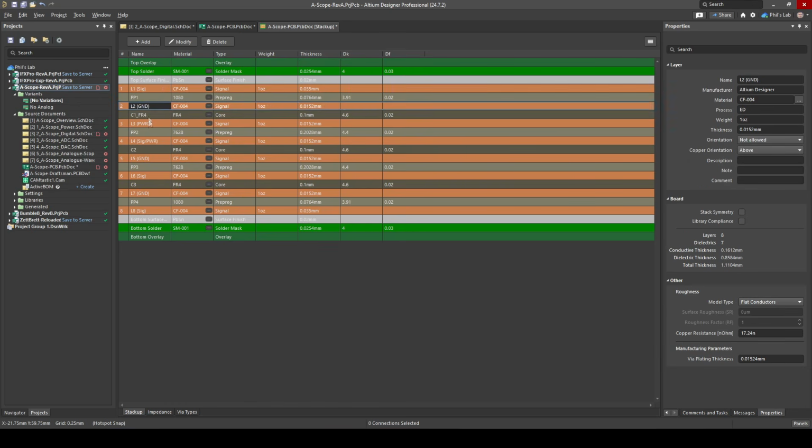Again, we have signal, ground, power, signal, ground, signal, ground, signal. So adjacent to every signal or power layer, we have a dedicated ground layer. So that means 3 of my 8 layers are entirely dedicated to ground. My main routing for these Ethernet signals will be on layer 1 because most of my componentry is on layer 1, and this is a microstrip with a ground reference right below, but I will also be using layer 6 to do the majority of my RGMII routing as a stripline because we have shielding above with layer 5 ground and below as layer 7 ground. So we have microstrip at the top, layer 1, and stripline layer 6. Again, ground adjacent to every signal layer.